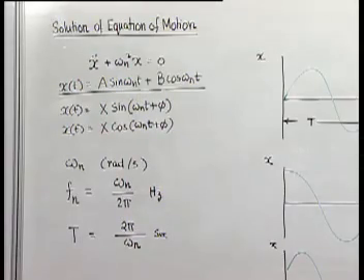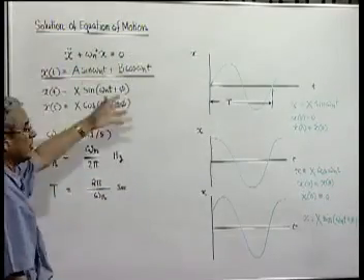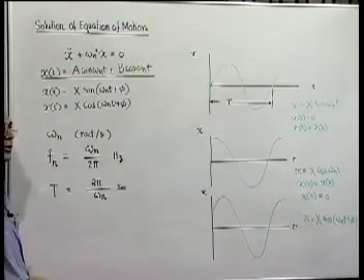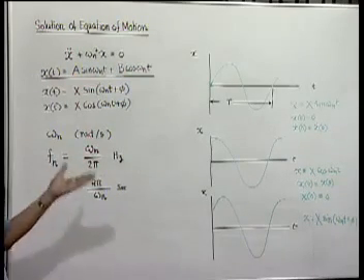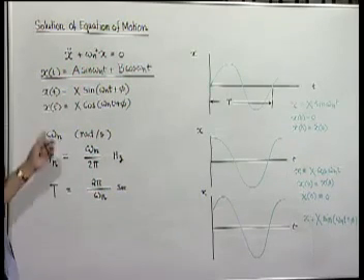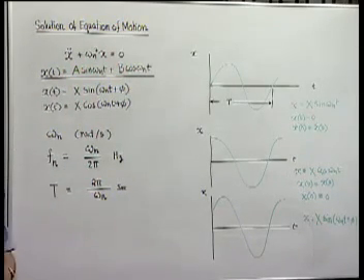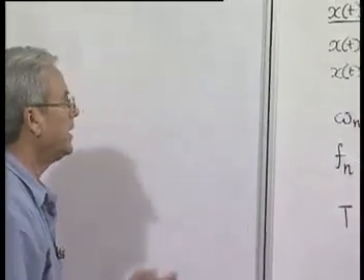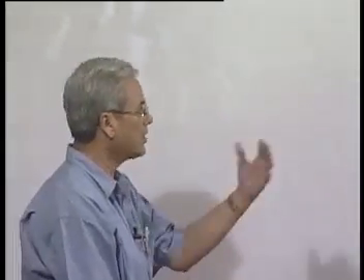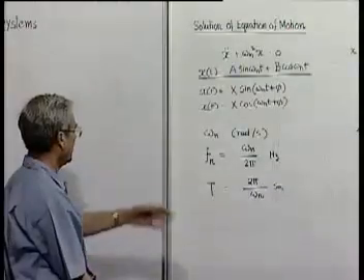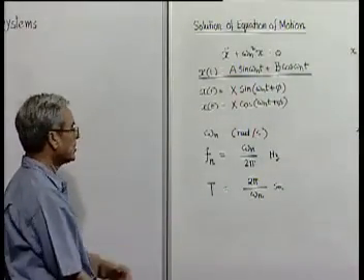So, therefore, we have found a very important thing: all single degree of freedom systems without any damping, if disturbed from the equilibrium position, execute oscillatory motion where the displacement for small oscillation can be represented by a simple harmonic function of time, and it vibrates with a particular frequency and time period, which is a characteristic of that particular system, and its value depends on the parameters. We will solve some problems to find out how this omega n or fn or T are found.